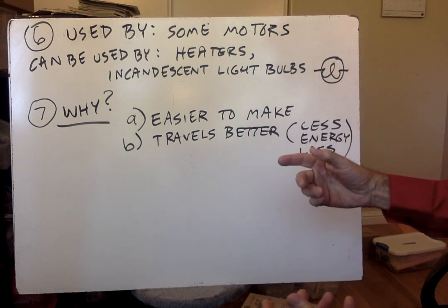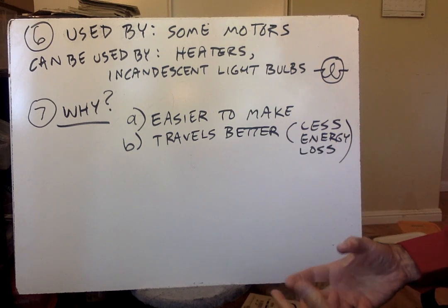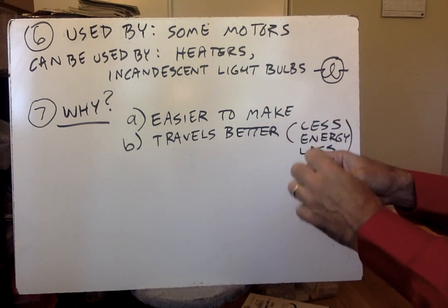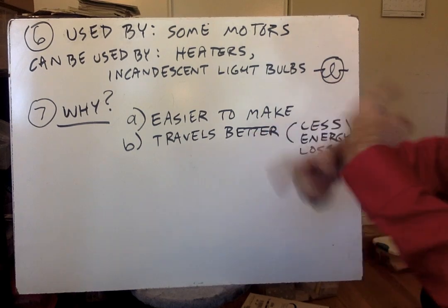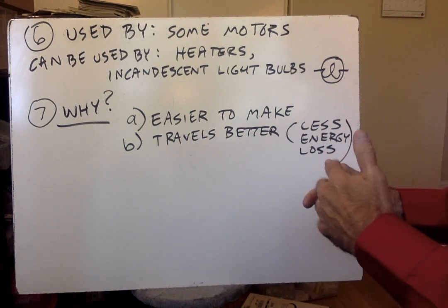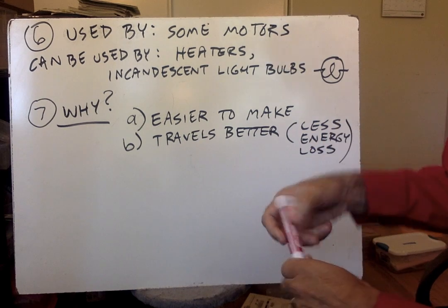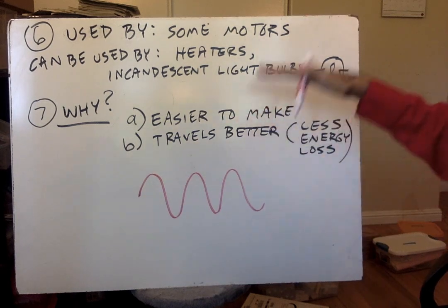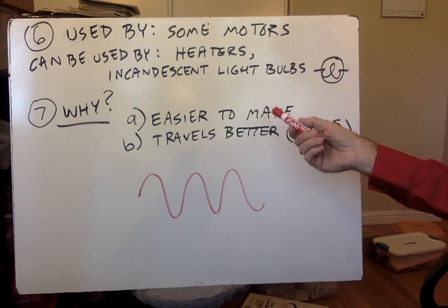The most efficient way to generate electricity from something moving, say moving water or boiling water and making steam and making it blast and turn something. If we can make a wheel turn, the most efficient way to make electricity is to use magnets and use a generator. And when you do that, it creates a voltage that looks like this. So generally, AC is easier to make traditionally.